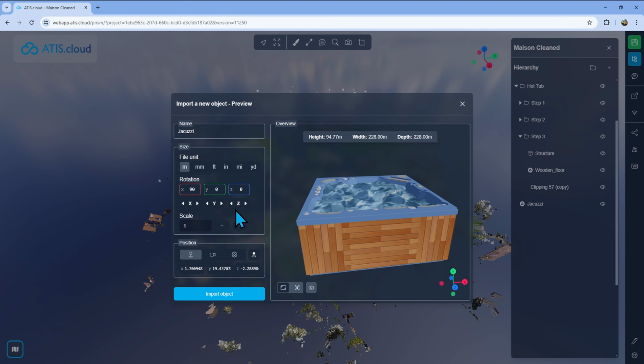Okay, so for that patch of grass, I have one clipping box that is only clipping inside, and for this one I'm going to have the other way around. I have clipping boxes that are cutting outside. So it's like gravel front, and then it hides what's in front. I have gravel right outer, and that's going to hide this. I have the left outer, which is going to hide this. And I have the gravel back, which is going to enable me, like this, to make the differentiation between the gravel and then the grass.